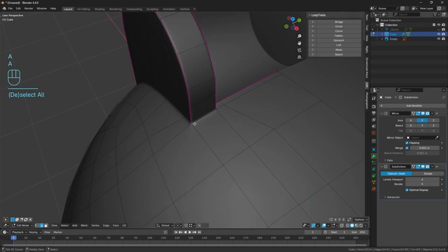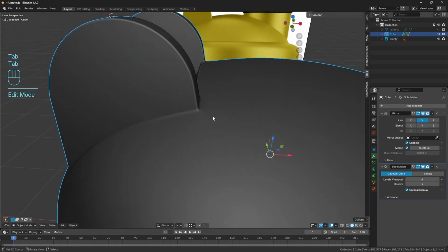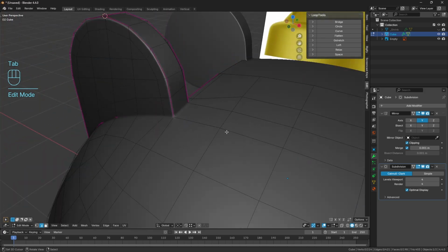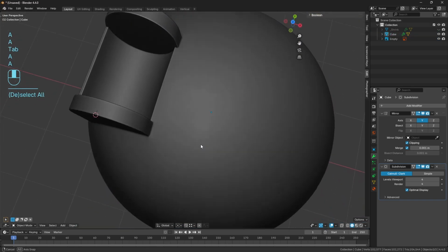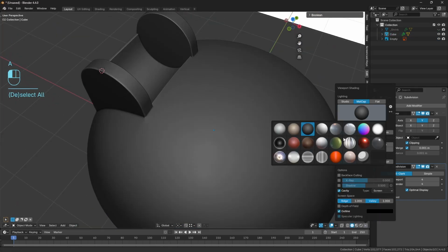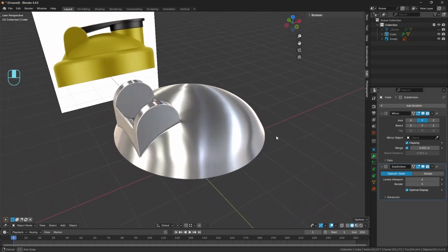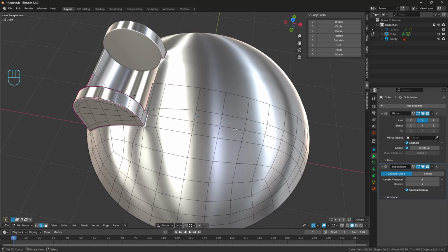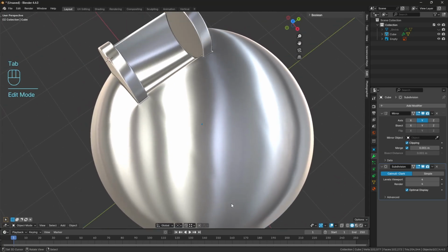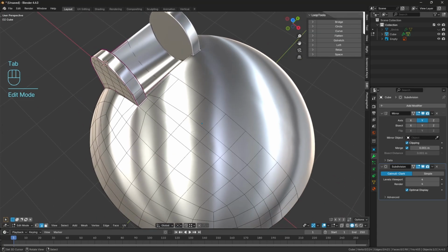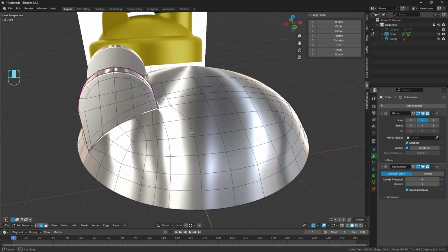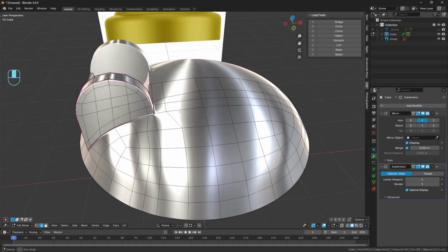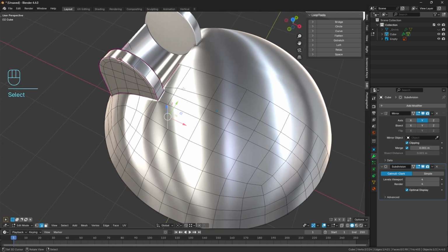And we can probably do the same here because this edge bleeds out a little bit more than I'd like. So I might just grab these, double tap G, and just push it in a little bit. Just get something like that. Cool. So let's just have a look at the curvature of this. I can see a little bit of distortion down here where we've added in an extra loop. And you can very easily see some distortion running through the middle here. So, before we resort to using our guide mesh, let's just do some general spacing of all of this.